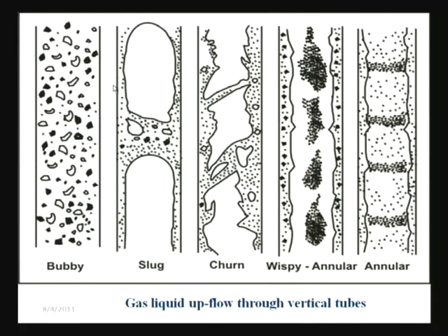In this region the wall shear stress is in the upward direction, and in this region it is in a downward direction, again here upward, again downward. So, with position we find that the wall shear stress keeps on changing its direction. This is also one particular way of distinguishing or identifying slug flow from the other flow patterns.